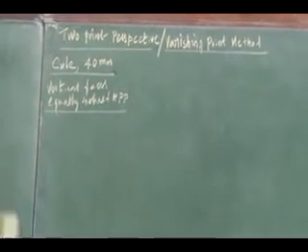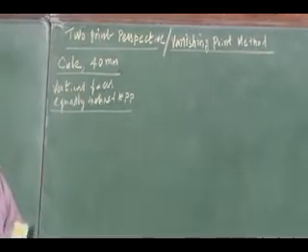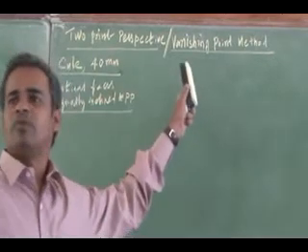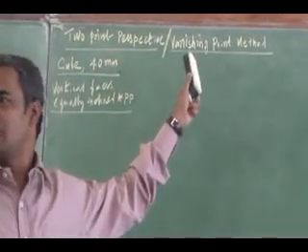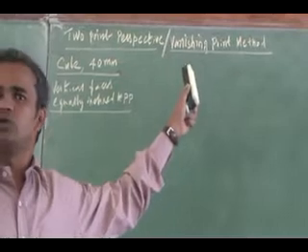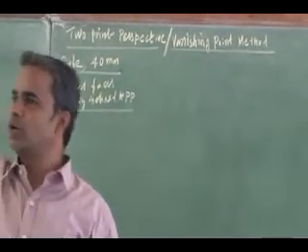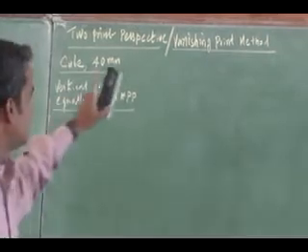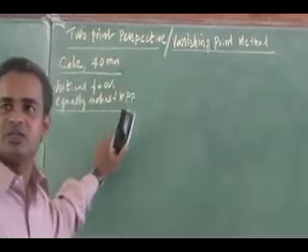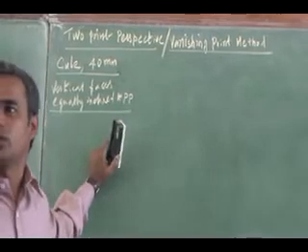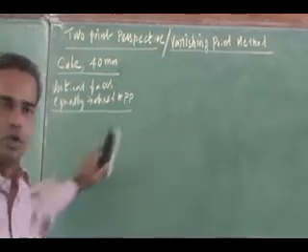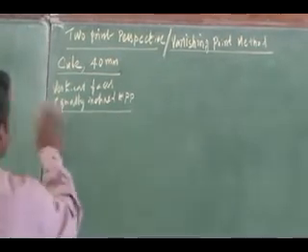That's why if vertical faces are inclined to the picture plane, I can adopt the vanishing point method, that is 2-point perspective. It is not wrong if you do it in a single point perspective. The type of method is not mentioned. You are asked to draw the perspective view, so you can adopt any one method.